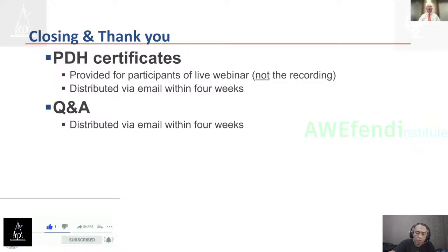Sure. Okay. So let's talk about low and mid-rise buildings for a minute, where the standard would allow the use of either method. I will say my practice in the last 12 years has been definitely weighted toward high-rise construction. And so for high-rise work, we always use dynamic methods of analysis, so modal response spectrum analysis and nonlinear response history analysis or linear response history analysis, because the dynamic behavior of a tall building is different from that of a short building.